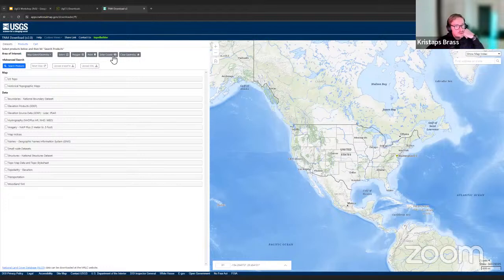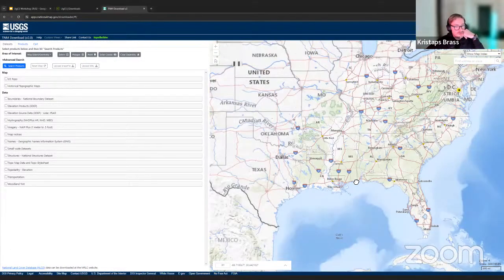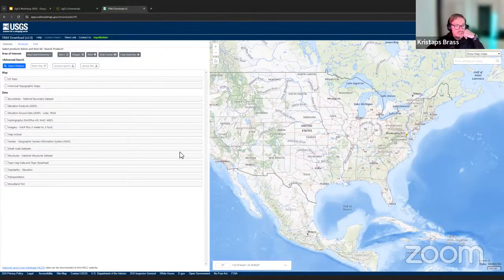So this is the United States Geological Survey. There's a high degree of similarity between UgCS and USGS, so just don't mix them up. But in any case, you can use both of them together. This service is really great for when you need accurate elevation data, because we have 1 arc-second elevation data, but from here you can get even more accurate. You can get, for instance, 1/3 arc-second data, which is a 10-meter distance elevation layer.